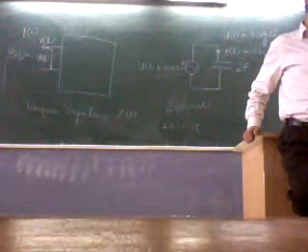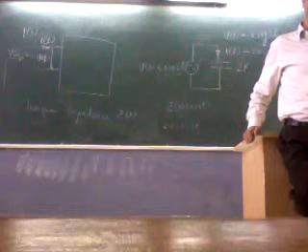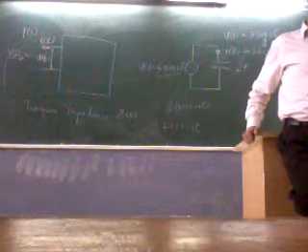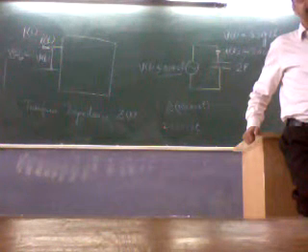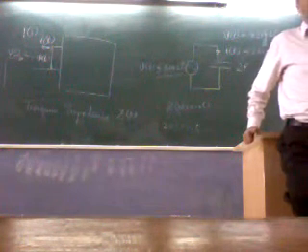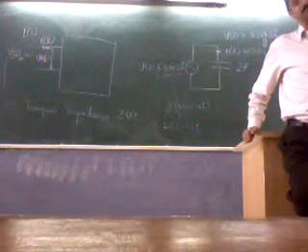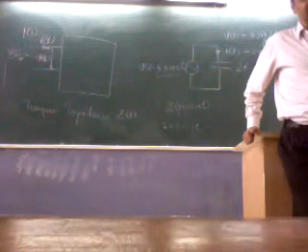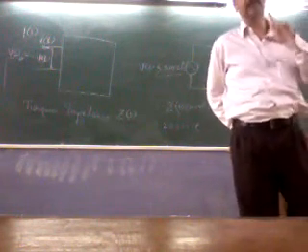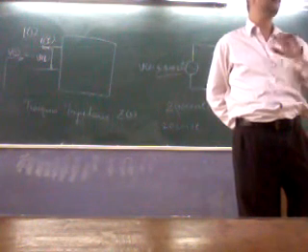For a given frequency, a sine wave of 50 hertz, how is it described? A sine wave of 50 hertz is not a unique description. There can be many such waves. To make this description unique, we need two more things. What are those? Amplitude and phase. So the relative relationship between the amplitudes and the phases of these two sinusoids can describe their relative relationship or ratio fully. When we take the ratio of two sinusoids, we take the ratio of amplitudes and the difference of phases.